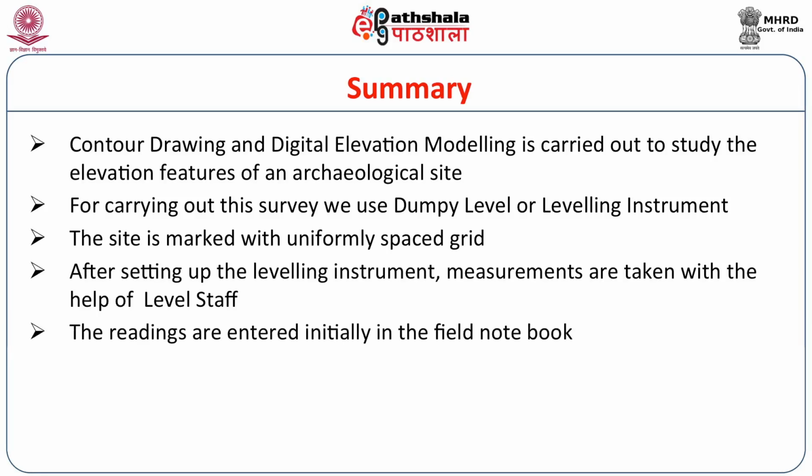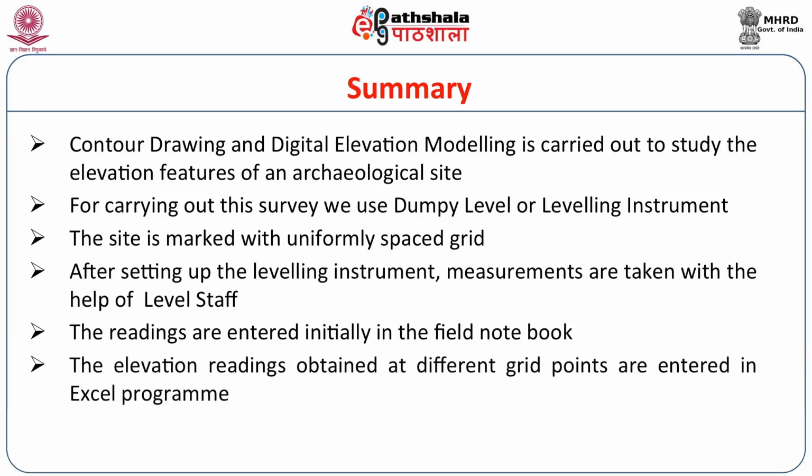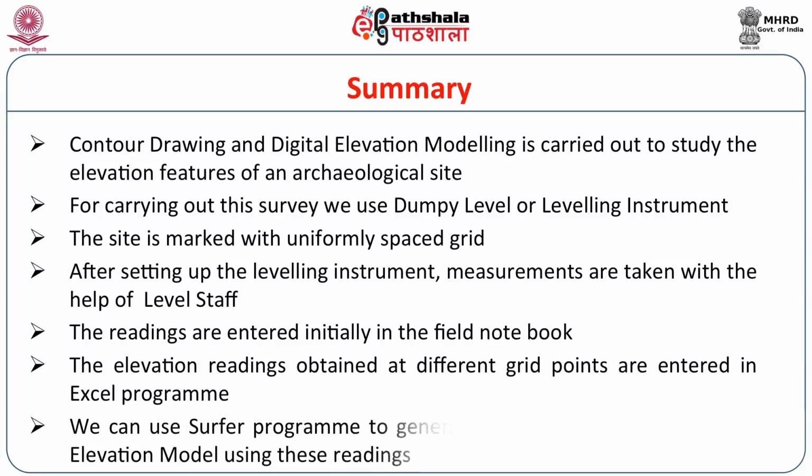The readings are entered initially in the field notebook, and afterwards the elevation readings obtained at different grid points are entered in the Excel program. We can use the Surfer program to generate elevation contours or a digital elevation model using these readings.